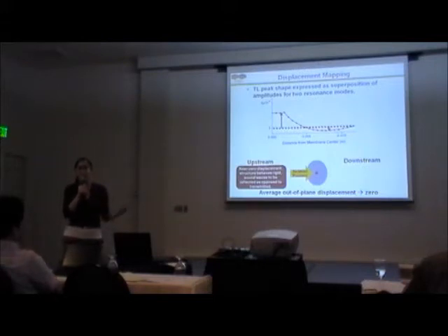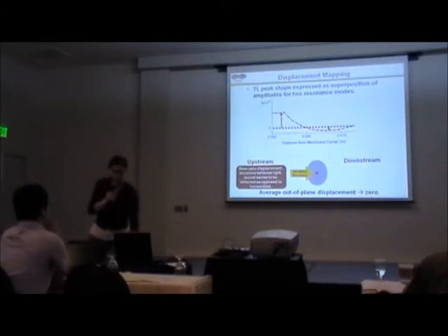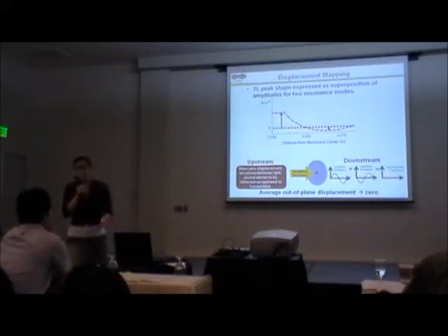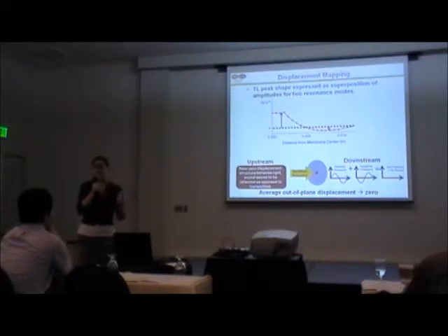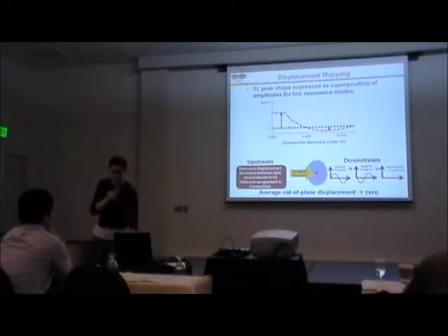moved. The waves are reflected back as opposed to being transmitted across the structure. Downstream of the structure, because of these positive and negative displacements, positive and negative pressure waves are generated and cancel each other out so that they are not able to propagate into the far field. This results in an overall high transmission loss when you combine these two methods of sound insulation.